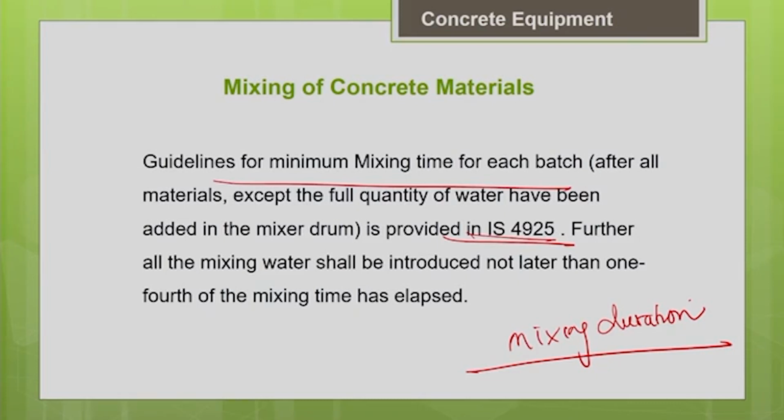The mixing time actually starts after all the materials are added into the concrete mixer machine, except the full quantity of water added in the mixer drum. That means your mixing time starts counting after all the materials are added into the mixer machine, other than the full quantity of water, because commonly you can see that the water is added in parts. This is because you may add some amount of water with the superplasticizer. We break it into parts because we add the water in stages to avoid loss in workability due to different reasons. So, that is why it is mentioned like this.